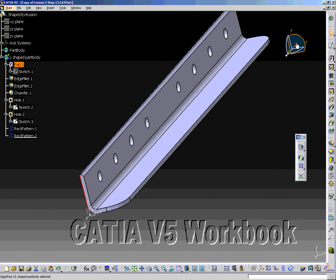One other way to rotate a part is using the compass, located in the upper right-hand corner of your screen. The compass can be used to perform many different tasks besides rotation. One way the compass can be used to rotate a part is to hold the left mouse button down on the free rotation handle and move it around. You will notice that as the compass pivots, the part will do the same thing.